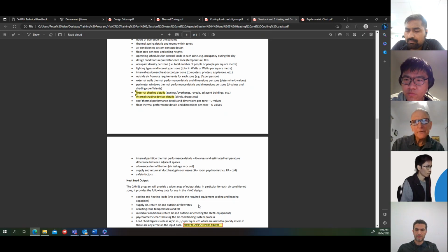So I think don't oversize it again. 0.25, if you want to put something in, put it in. If it's an old building that's got old rattly windows and things like that that might leak, then maybe you need to allow half an air change an hour for leakage.